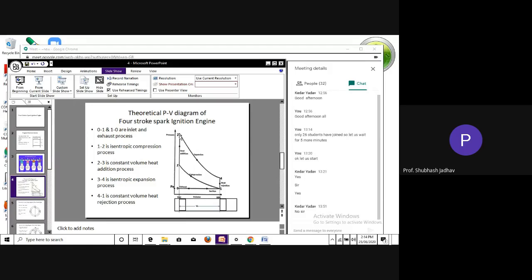Now piston starts its motion from TDC to BDC. So when the piston starts moving, what happens to volume? Volume goes on increasing. So the volume is increasing means the line should move towards the right. Okay. So it is moving towards the right side. Towards this side it has to move. But what is happening to pressure? Due to the increase in the volume, the pressure inside the combustion chamber is decreasing. So when the pressure decreases, the line has to come down.